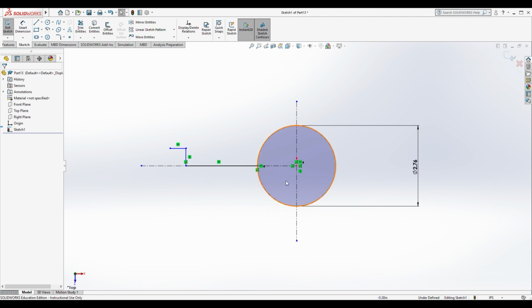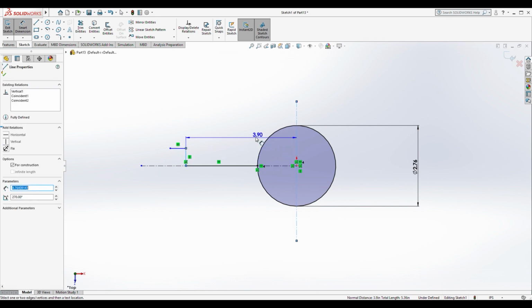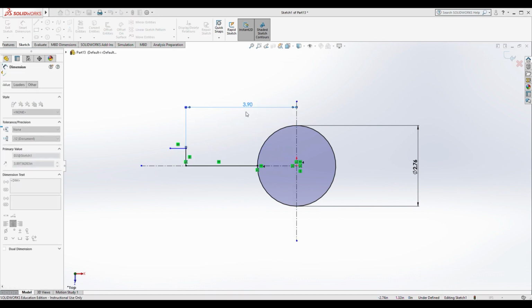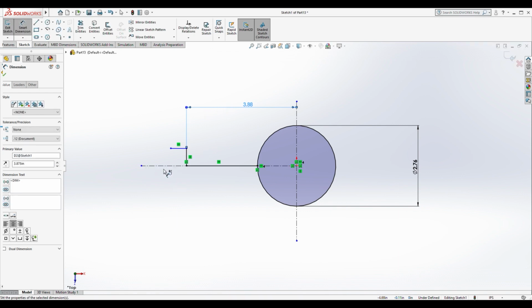Okay. And so we still need to get that stuff dimensioned, right? So let's take a look at the dimensions. Overall, from here to here, it's 7.75 divided by 2. So we're going to go ahead and click this line right here, and what I'm going to do is just type in 7.75 and then divided by 2, and it's going to just do the math for you. So that goes to 3.875. Okay.